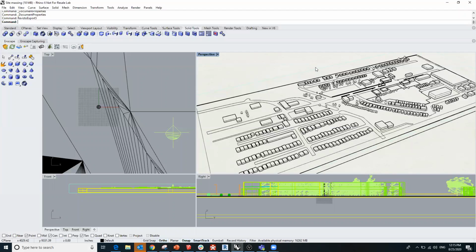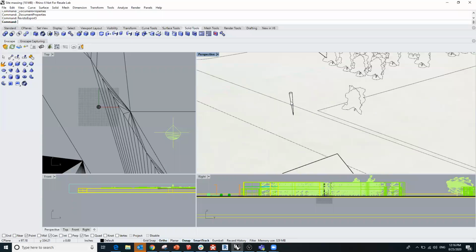What I like to do is generate a point or object in the model that I can easily identify as my positioning point. In my massing model, I created a cone object, and then I positioned my geometry to read this point at the 0, 0, 0 XYZ coordinates. So I'll be able to use this cone object I created in Rhino, and that gives me a way to easily look for my zero origin point.